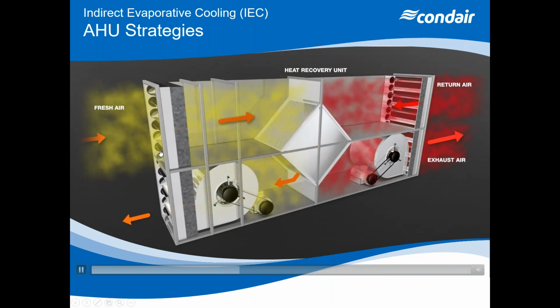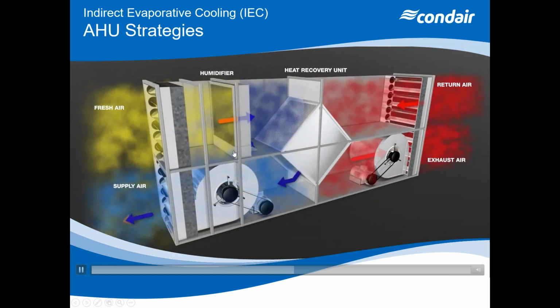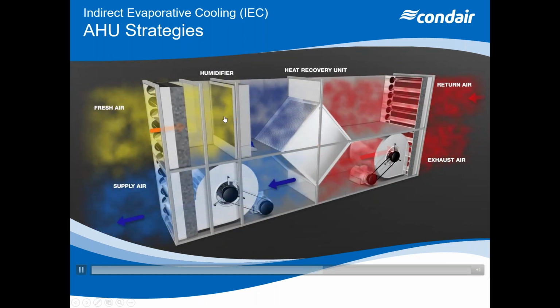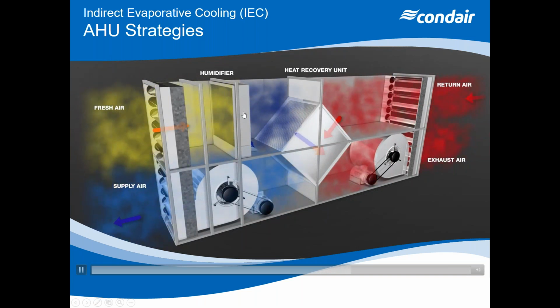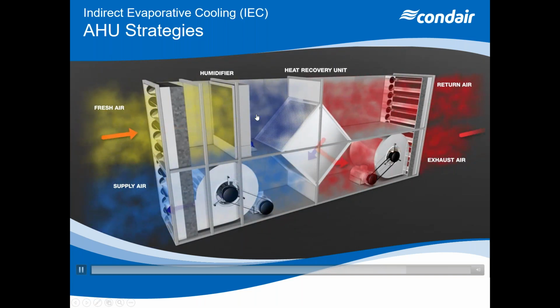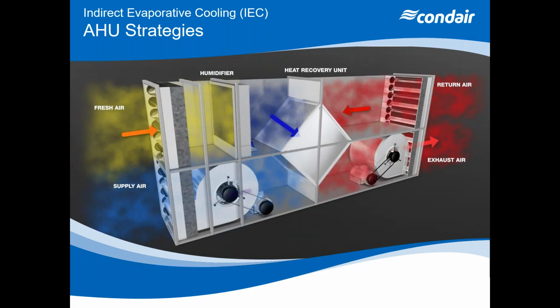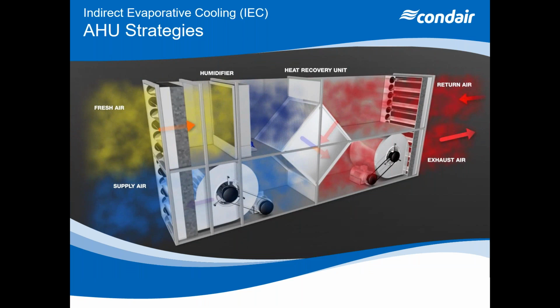And what we do is we take our fresh air and we run it through an adiabatic humidifier and we cool that fresh air. And we'll take that line of enthalpy right up as close as we can to saturation. We'll evaporate as much moisture as we can, so we'll be increasing our moisture content to the maximum potential.